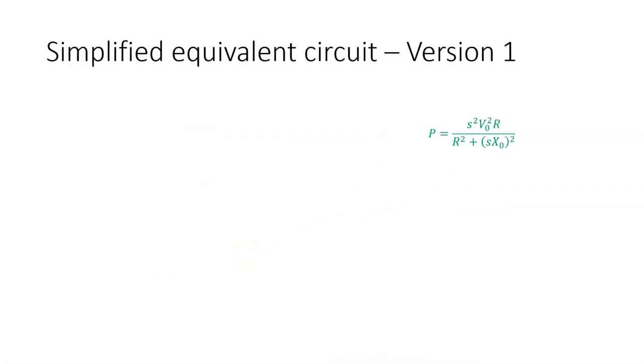If we now look at the mechanical power, so power is torque times omega. Omega is normally 2 pi times the rotational speed in revs per second. But on the rotor side, that speed is going to be multiplied by the slip. So it could be 90% of that or 80% of that. So that's omega R. So the power then is the torque times, instead of omega, I'm going to put in S 2 pi N1. And we're going to rearrange that then to get the torque.